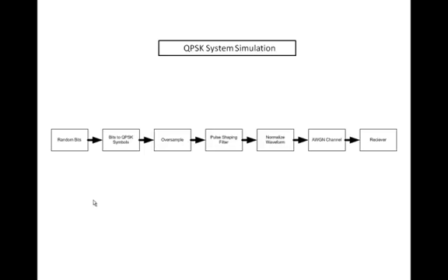Next, for the signal generator, I had to normalize the waveform. The reason being is that when it plays back the waveform, the DAC of the SIGGEN, the digital to analog converter of the SIGGEN, sometimes it clips. There's clipping at the DAC, so you have to normalize the waveform. Next, it's passed through an additive white Gaussian noise channel, and then fed into a receiver.